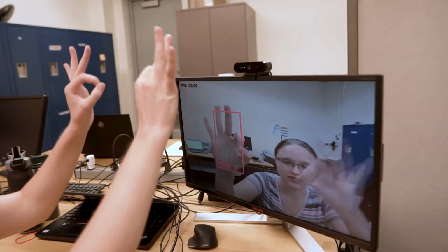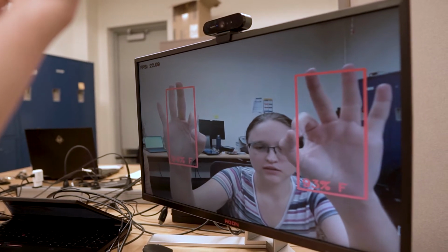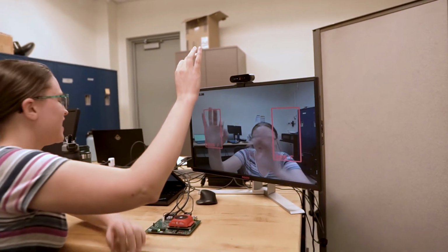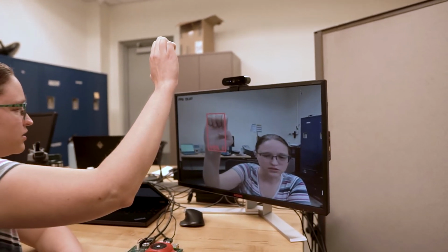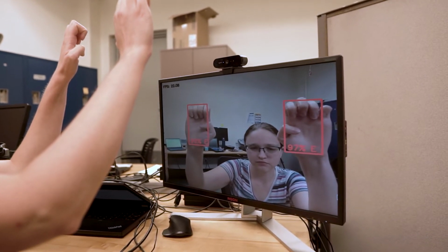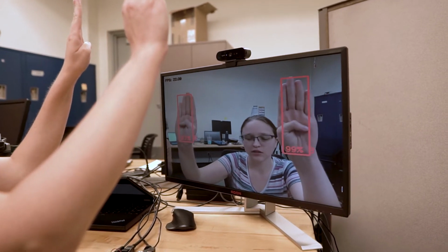The goal of this project is to design an engaging portable demo that focuses on the acceleration capabilities of an FPGA. A custom carrier card was designed for a Xilinx SOM containing the Xilinx Ultrascale Plus MPSoC architecture, and a machine learning model that we train to identify and interpret the static letters of the ASL alphabet. The model will then be accelerated using a Xilinx DPU.